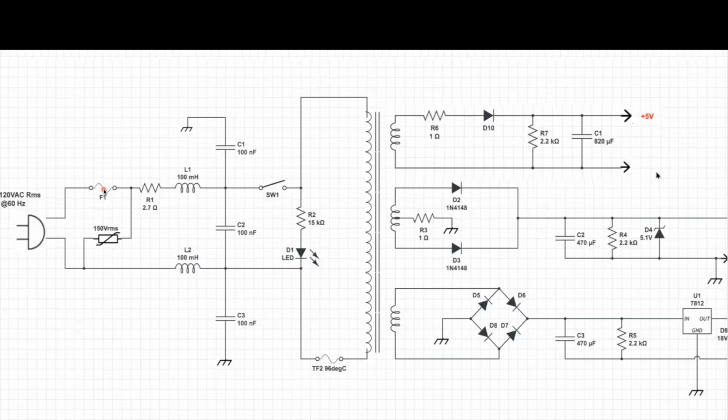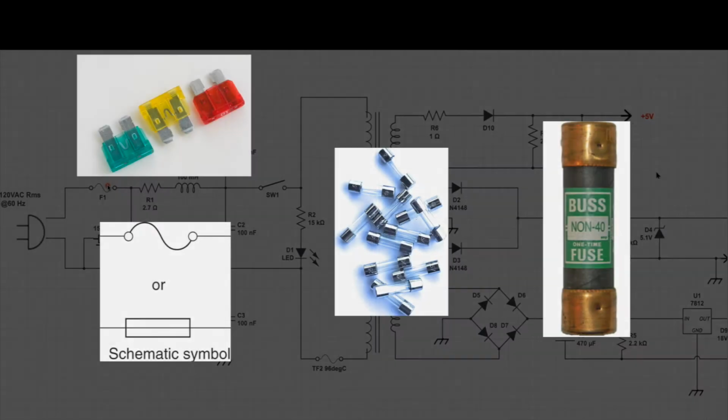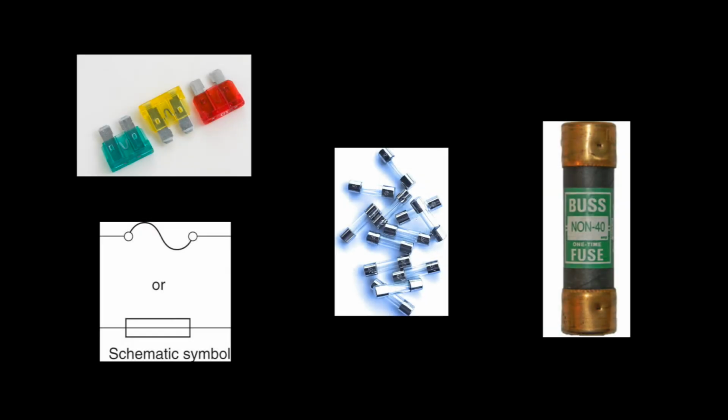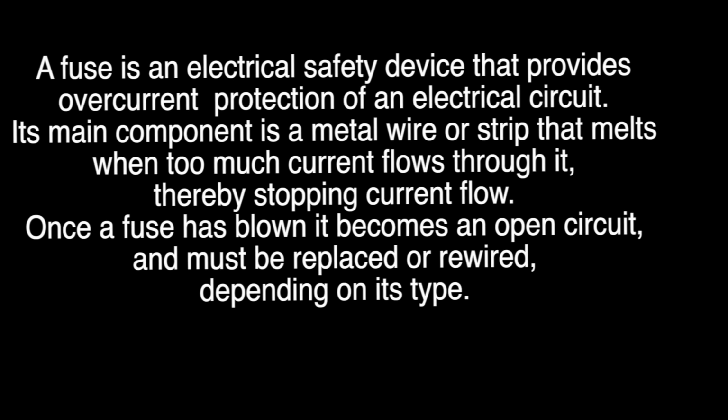What is the job of our protection fuse? Moses? Very good. So essentially, if for some reason too much current flows through a fuse, he says it blows. Well, if you look inside a fuse, what does it look like? A very thin piece of wire, a very thin piece of metal. It's basically a small conductor that can carry just enough current. And if it exceeds that value, it overheats and melts.